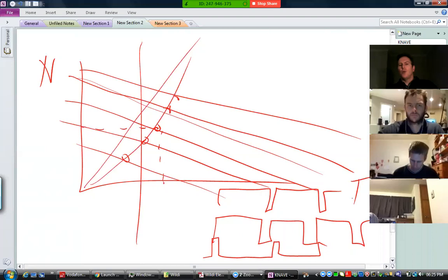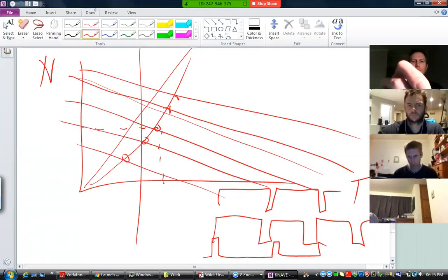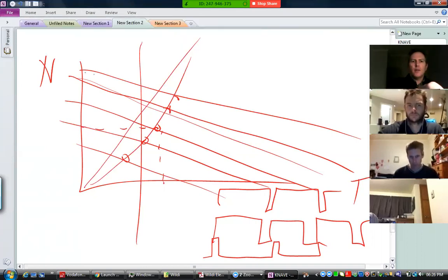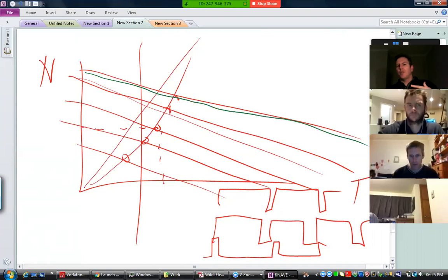Whereas if you increase the armature path resistance by putting, let's say, a variable resistor in the armature path, what'll happen then is, if this one was your original graph at full voltage, you won't change the voltage, you'll just change that resistance value. That resistance value will have the effect of making this graph steeper.